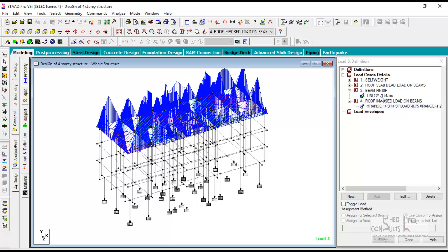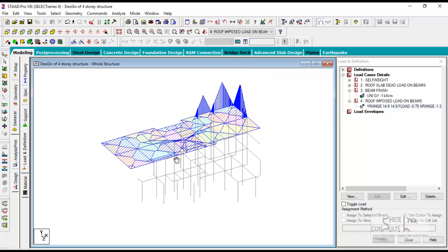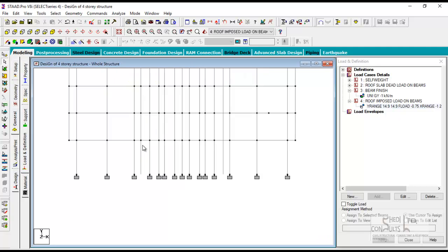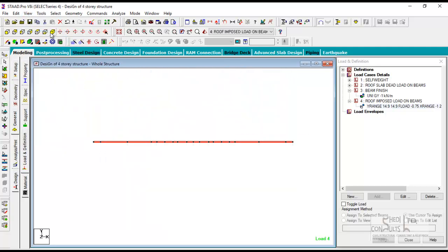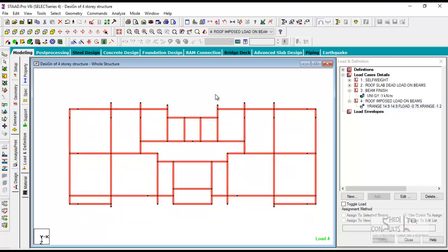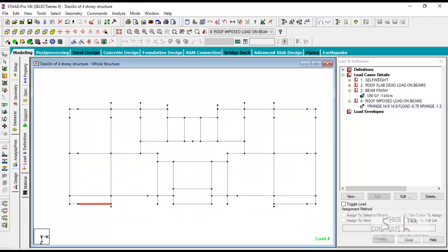Okay, so I will create wind load last. So let's leave that for now. Let's create the load cases on all the floors, and then we will treat the environmental load lastly. So let's go to the 3rd floor. Right.